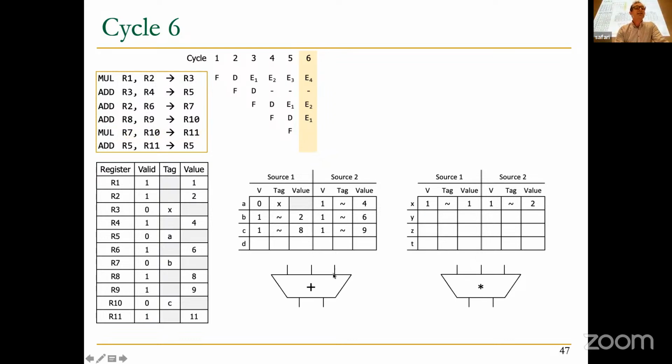So the reason it can start executing is multiple. One is the out of order execution machinery that we added, and the second is that the adder is pipelined. Because the previous add moves to the second stage of the pipelined adder, and the second add moves to the first stage in the pipelined adder. Okay, so there's pipelining happening in the adder also. Alternative is providing a second adder, of course, right? Like we have done in the earlier parts of pipelining, if you remember with the dryer, right?